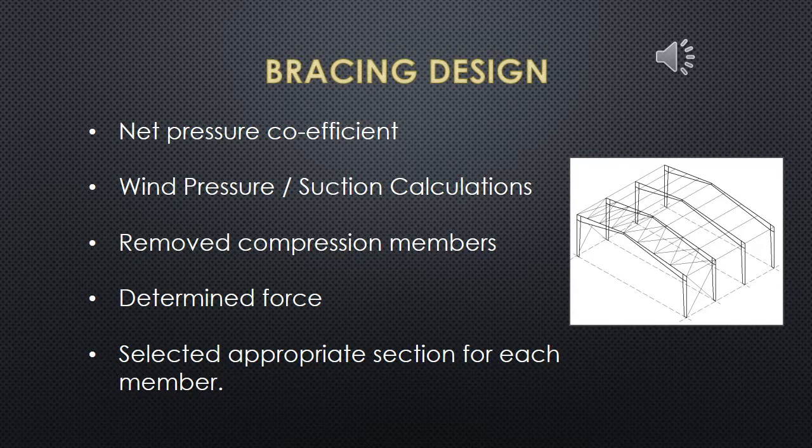We then moved on to bracing design. The members of our group found that this part of the assignment was probably the hardest portion to work out. We started with determining the net pressure coefficients using the table in the code. We then determined wind pressure and suction calculations,